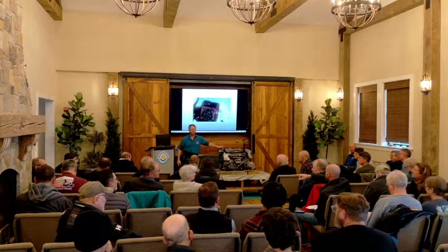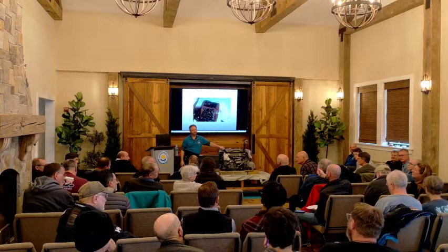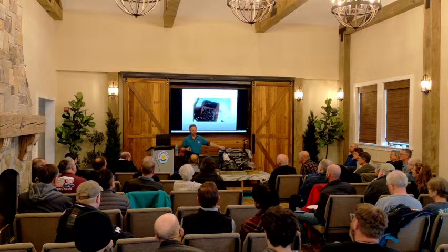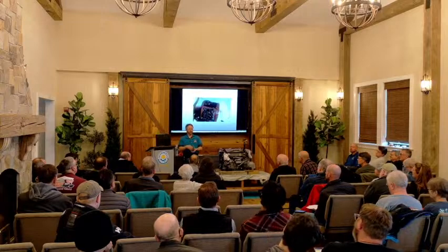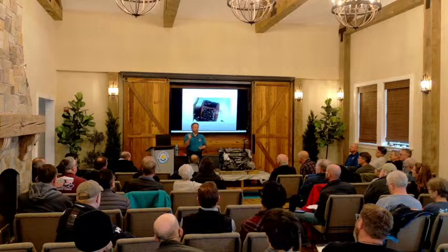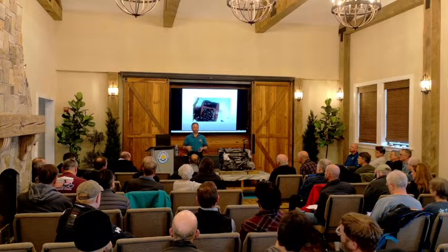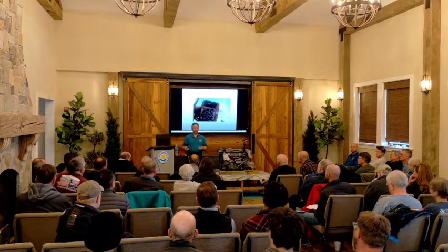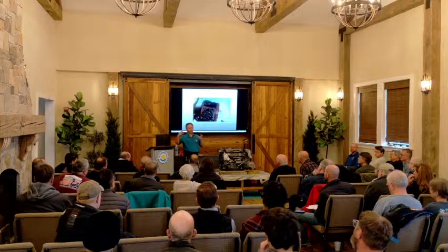The gentleman's comment over here on this sailboat, putting it in reverse, folding prop. Was there a service bulletin that came out where Yanmar says don't leave it in reverse? Is that true? Yes, some of them, the ones with the clutch cones, would get locked into reverse. And so when you actually try to put it back into neutral, you couldn't because it literally was locked in. When that problem first happened, people were pulling transmissions out and sending them back to the distributor. All you really need to do is, while lightly trying to put it back to neutral, bump the starter, and that jars it, which then pops it back into neutral.